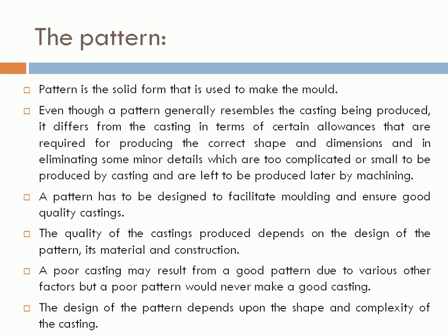and the design of the pattern depends upon the shape and complexity of the casting. What the importance of the pattern in the casting process is, you can easily understand with the use of this slide. Even though the pattern generally resembles the casting being produced, it differs in terms of certain allowances that are required to produce the correct shape and dimensions, and in eliminating some minor details which are too complicated or small to be produced by casting and are left to be produced later by machining. That is the pattern.